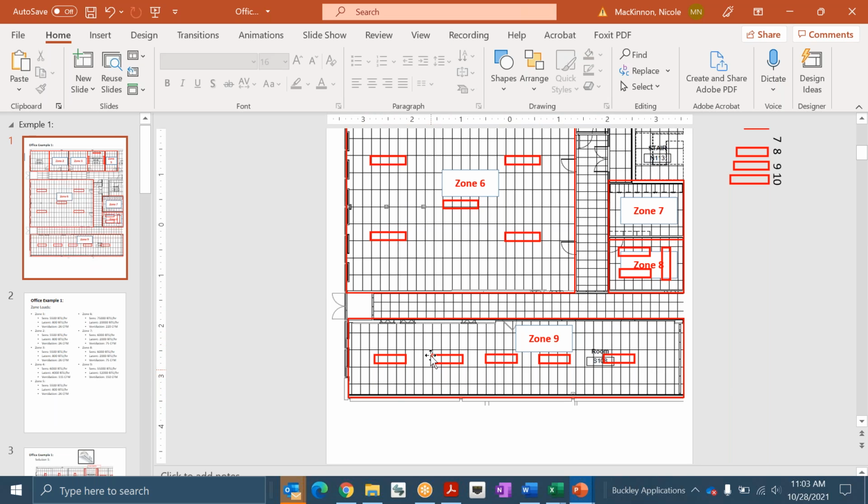So that checks out. Generally you want to see the beams in the middle of the space. If it's a two-way discharge, you want to throw against both walls from the center. You also could turn each one of these horizontally or vertically. The difference here is now I have to go back and look at my throws. I'm throwing at each beam. I want to make sure I've got enough space between these so I'm not going to have a draft condition right below. Maybe this is an open office. There's a bunch of people with papers on their desks. I don't want to blow those papers around.